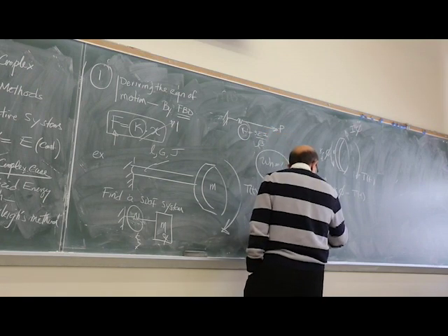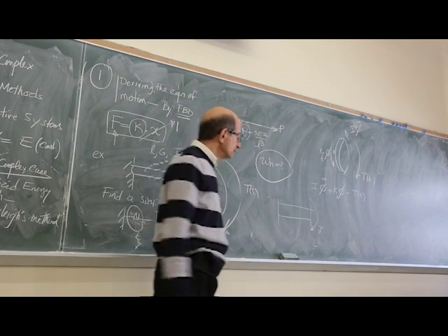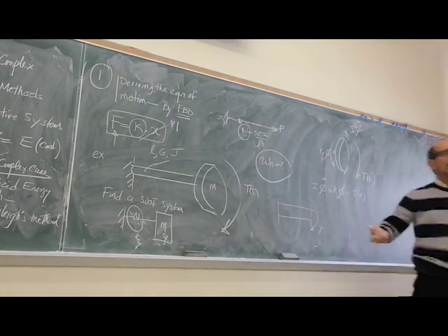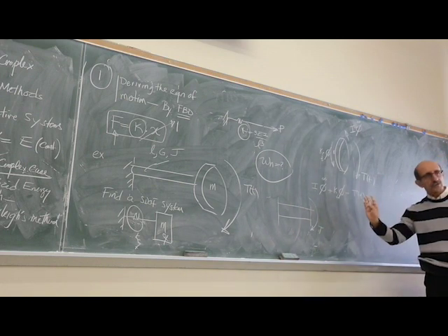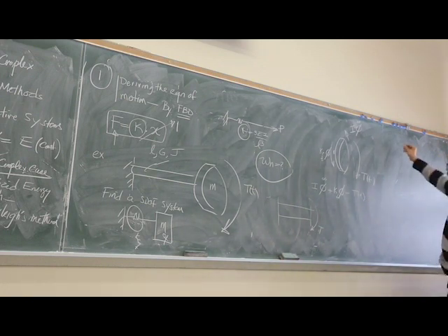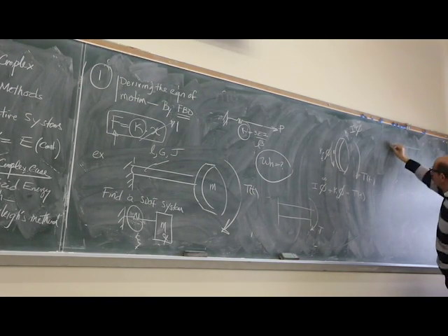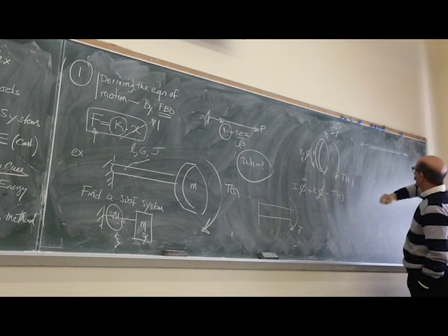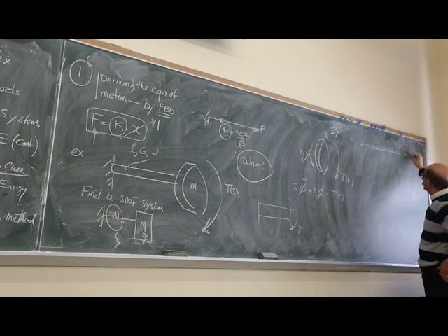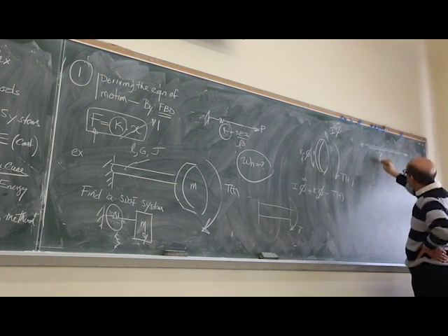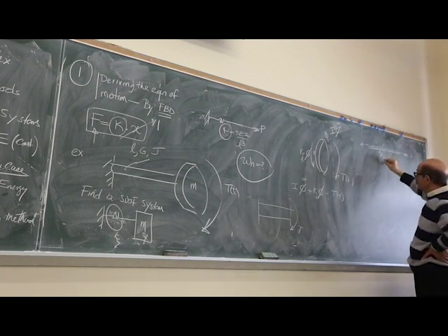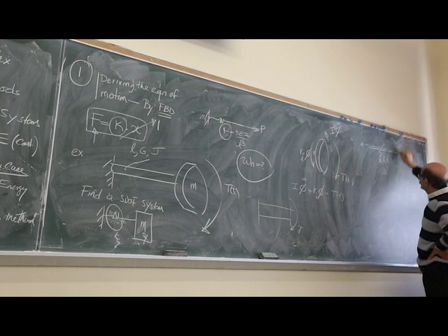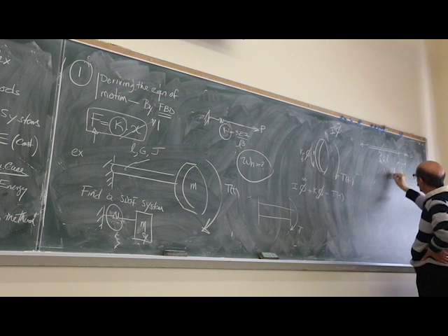When you have a shaft subjected to some deformation, do you remember the angular displacement of the shaft? If you don't remember, I'm sure you always remember this simple little guy from strength of material. If you have a bar subjected to a load P, and the properties are cross-section area A, modulus of elasticity E, length L, you remember the deformation that this will experience. Delta would be PL over AE.